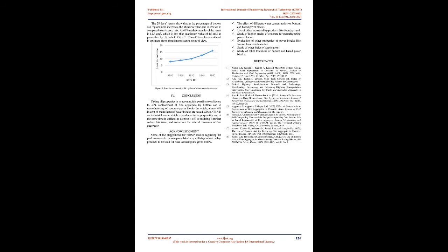At all the levels of replacement of sand by CBA, water absorption increases with respect to the reference mix. The individual water absorption of the specimens is within the code limit of not more than 7%. An average water absorption at 30% replacement level is 5.81%, which is less than 6%, hence is optimum from water absorption point of view.